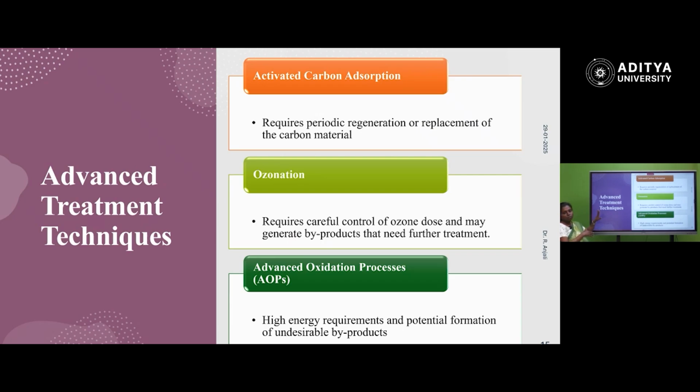So I'll give you an overview of the advanced treatment techniques. First, you can see that adsorption comes under the physical methods. Again, we have to regenerate whatever materials we used. Next is ozonation. Generally, ozonation will give you good results. The problem here is that control of the ozone dose is difficult, energy is required, and it also generates more byproducts.